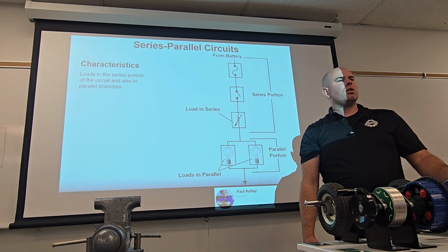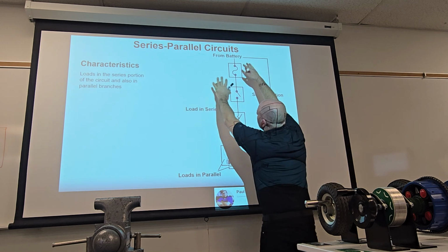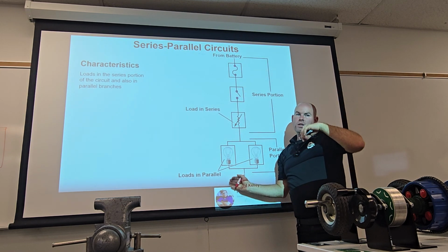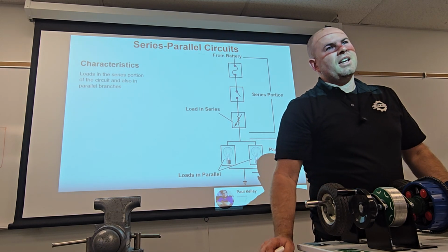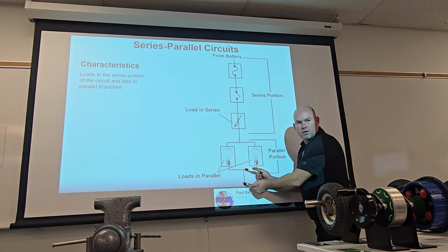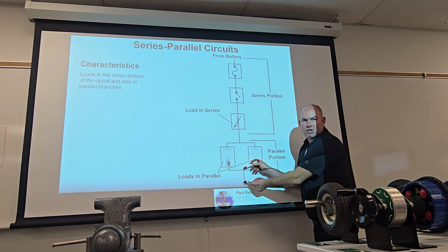So voltage drop, you could tell whether you're looking down here or whether you're looking up here. Make sense? Because remember, when the load doesn't work, it could be on the positive or it could be on the negative. So the load, shouldn't it be 0 though? Exactly. And right here, I'm showing that I'm dropping. So between this and this, it shouldn't be dropping voltage. It should be 0.